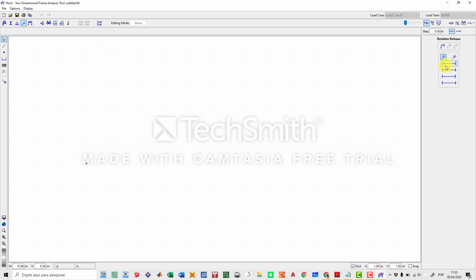You can let your structure have articulated connections, which is pretty much a pin connection. You can also use a fully restrained connection for your structure. Here we are going to be using only fixed connections, but when designing trusses, for example, you can release the rotation of a few members. And here you can also put deformation restraints. You can make a member flexible or not, and you can let a member be axially or shear deformable.